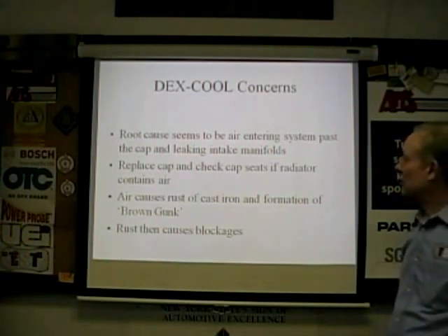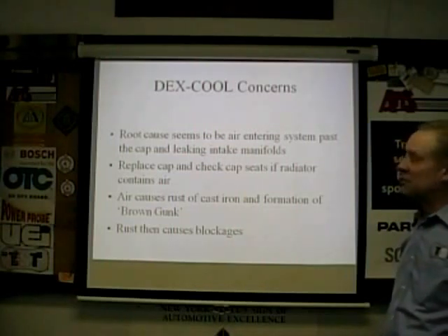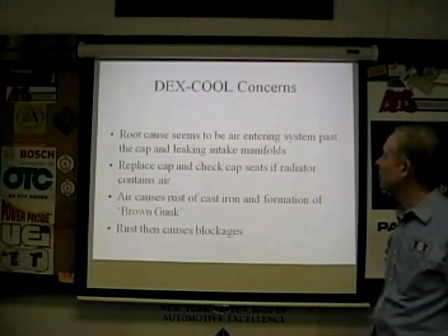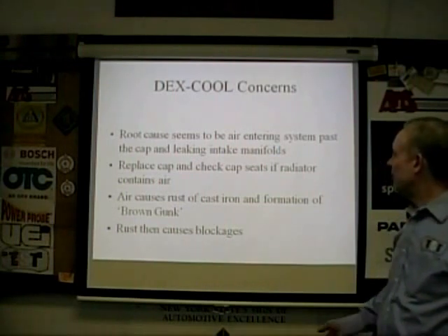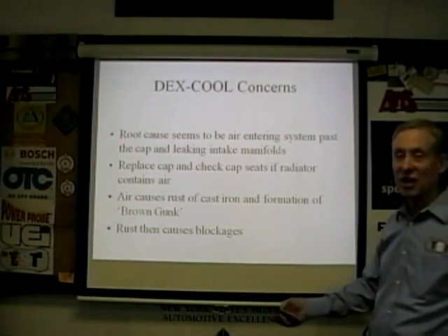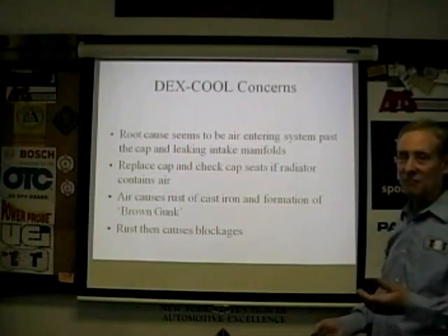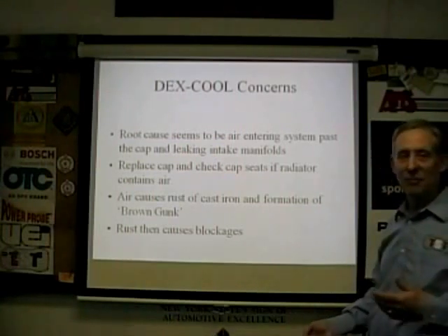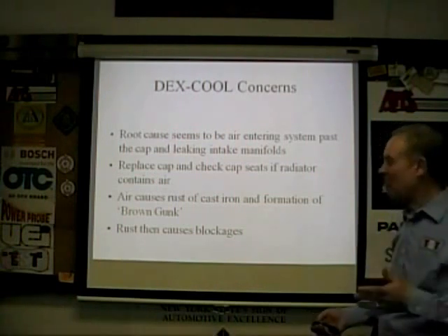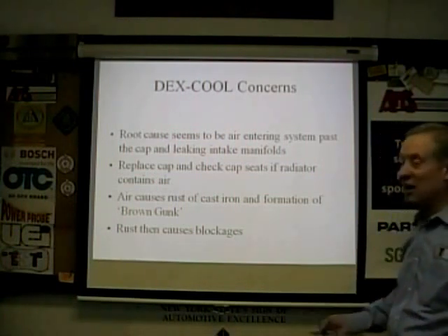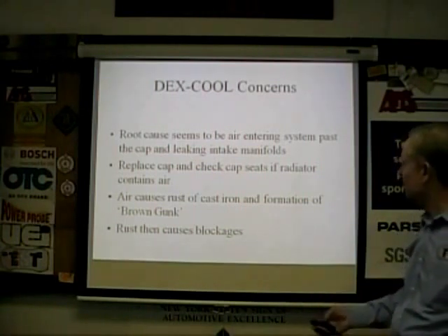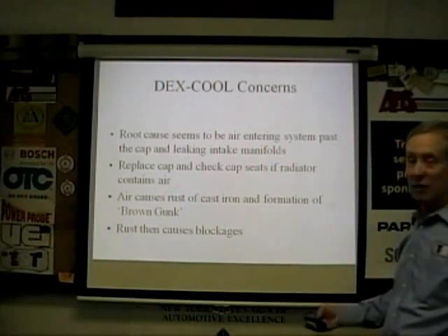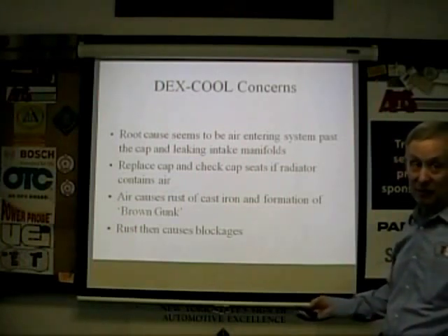Dexcool concerns that are kind of unique to OAT technology. Root cause seems to be air entering the system. You get aeration. You end up with a little chemistry change, and you end up with the brown gunk. This is not the jello effect. This is that mud effect. I'm not sure mud's a chemical term, but it looks like mud. And it blocks things up, causes local hotspots, overheating, and it's a real bear to get it out. Yeah, I've seen that a lot on GM cars. Yeah. We've seen it at Volkswagen to some degree.